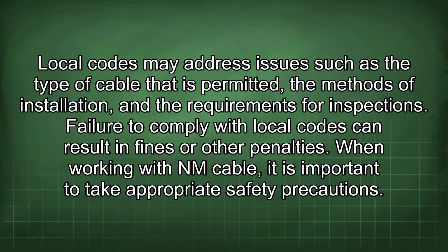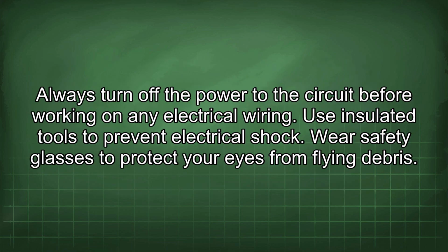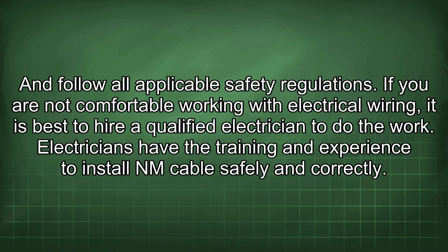When working with NM cable, it is important to take appropriate safety precautions. Always turn off the power to the circuit before working on any electrical wiring. Use insulated tools to prevent electrical shock. Wear safety glasses to protect your eyes from flying debris. And follow all applicable safety regulations.